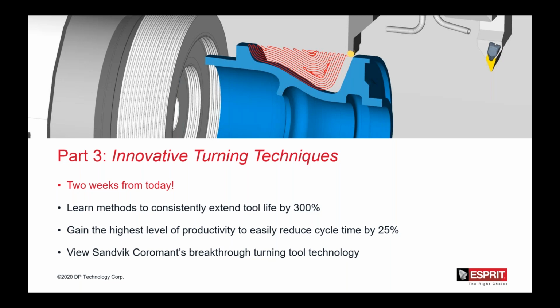Well, my thought is solids when you get 5/8 and below, 1/2 inch and below, and then once you start hitting that 1/2 inch, 5/8 diameter, then replaceable heads and indexable start coming into play. Freddie, do you agree? I do, along with the tolerancing required to the hole. Yeah, definitely. Carbide's going to have a tighter tolerance hole than an indexable and better finish. Yes.